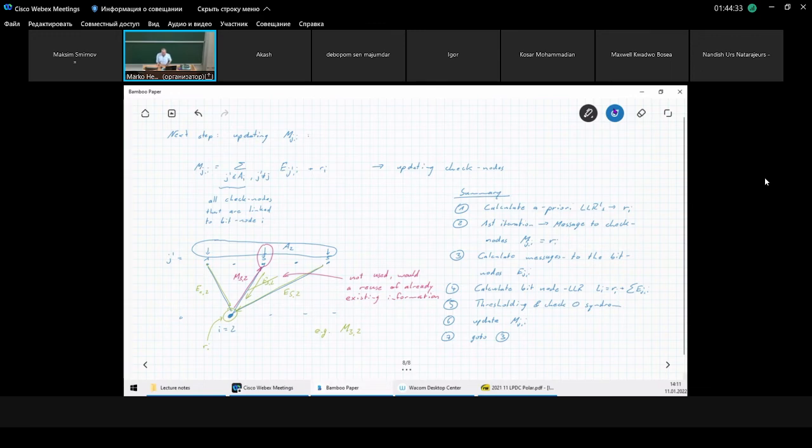So obviously the MJI is the extrinsic information on check node 3 here in this case that we can get from using the other check nodes, or basically from the observations on the other check nodes, we can get information on this desired check node. So I would call it the extrinsic information for check node 3 that we can get from using the other check nodes.